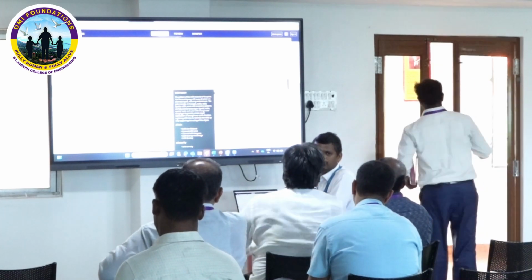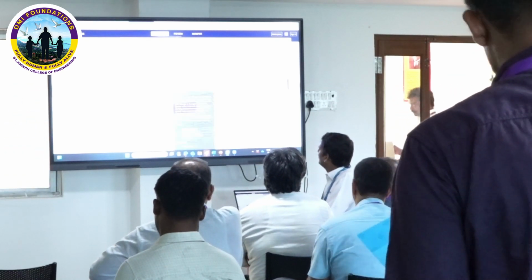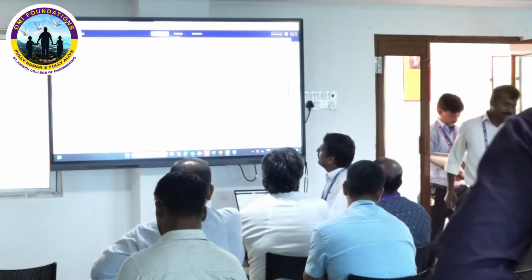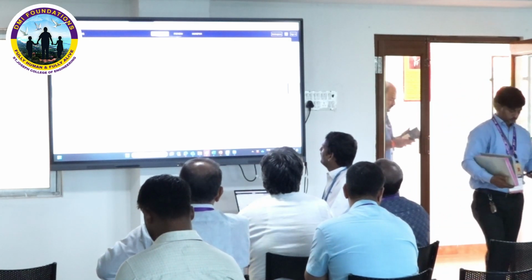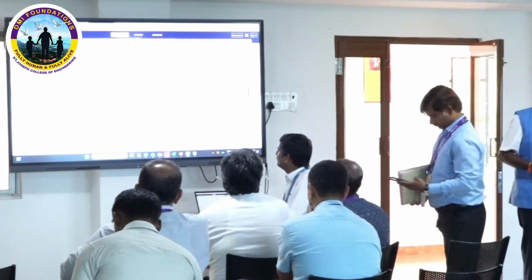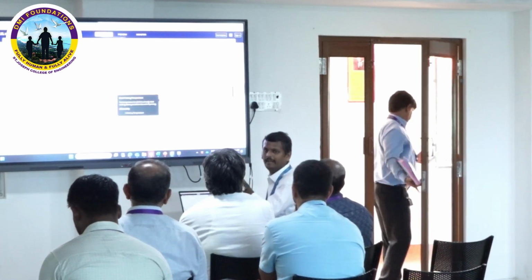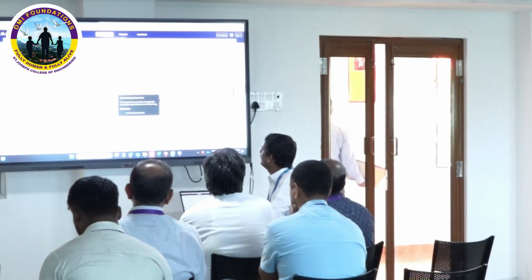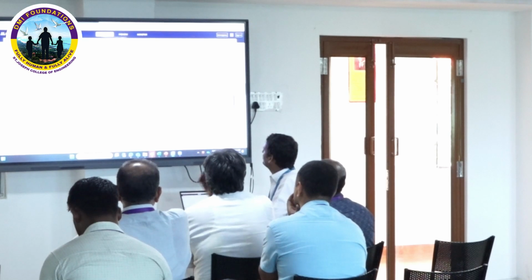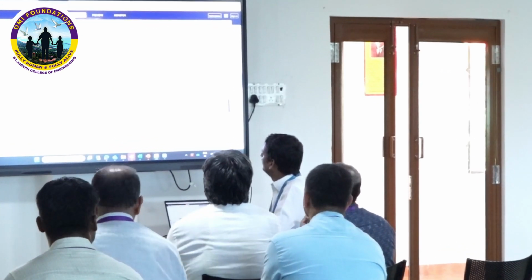So maximum you can go for 80%. That can give you good strength. Same way, whenever you are changing the material here, automatically the printing temperatures will change, and the build platform temperature will also change. But we need not look for it, since we are already maintaining those temperatures in the material itself. Same way the printing speed, we are maintaining as it is. We are not making any change in this.